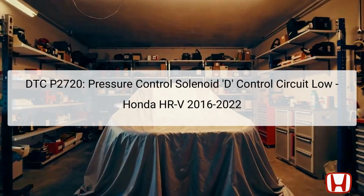This presentation focuses on DTC P2720, which stands for Pressure Control Solenoid D Control Circuit Low, specifically for the Honda HR-V models from 2016 to 2022. This fault code reflects an issue within the electrical circuit corresponding to the Pressure Control Solenoid D of the Continuously Variable Transmission, CVT. Important to note, the error pertains solely to the electrical circuits and does not indicate any mechanical failures within the transmission itself.